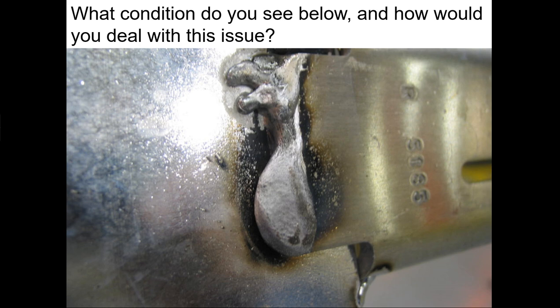Now, this one, I always like to throw this out there as, what do you think happened to this one? This one was being welded with a water-cooled gun, and the water-cooled gun started to leak. I just put it in there for interest's sake. You can see how the aluminum was literally quenched with the coolant and how it took on the shape. It, of course, needed to be completely ground out.